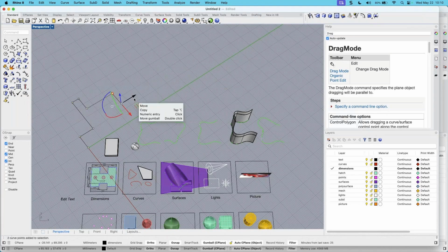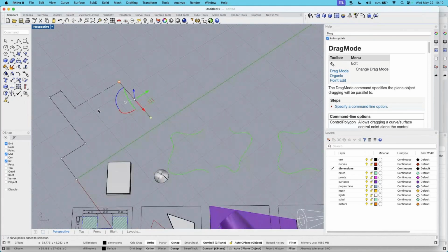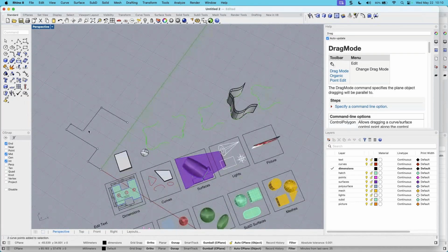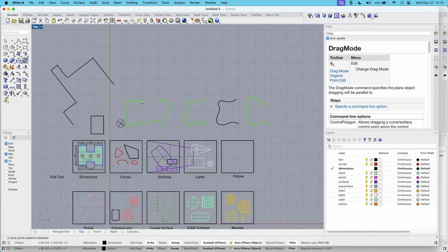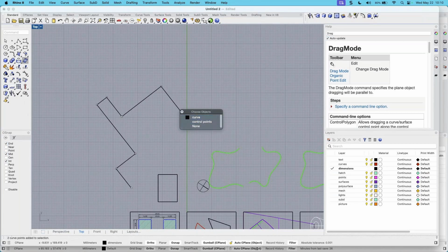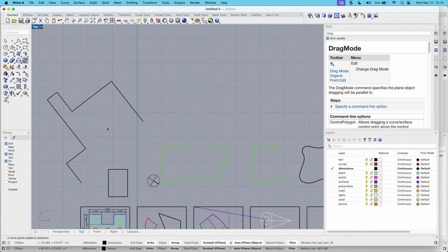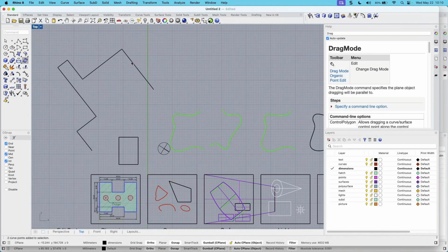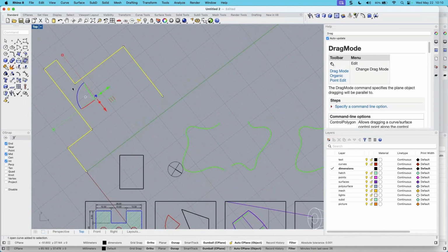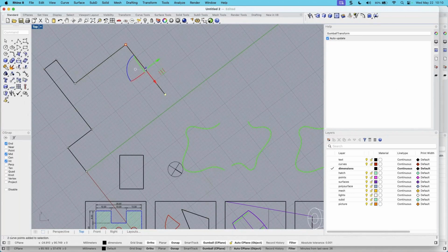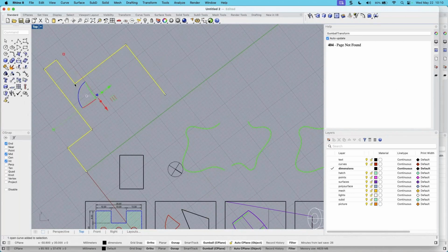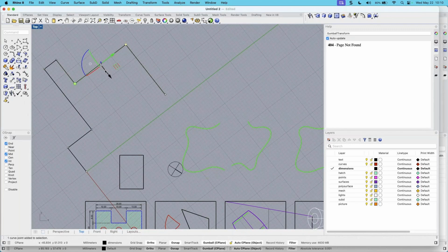Sorry, I was maybe not clear in my question. Like by a specific distance? Yeah. You absolutely can, but I want to start with that. Okay, you can do any distance you want. Since I decided to draw this at an angle, having auto cplane on is really helpful because then I get on that cplane. If I do a window around these 2 points, I want to move it a relative 2 units. See? So I pick these 2 points and I want to move it 10 units. See how it moves it?